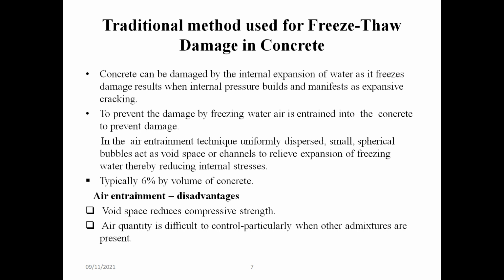This leads to the buildup of internal pressure, which can be manifested on the surface of the concrete as expansive cracking. To prevent the damage by freezing water, air is entrained into the concrete. In the air entrainment technique, uniformly dispersed small spherical bubbles act as void space or channels to relieve expansion of freezing water, thereby reducing total internal stresses. Typically, 6% by volume of concrete will be required for the air entrainment technique.